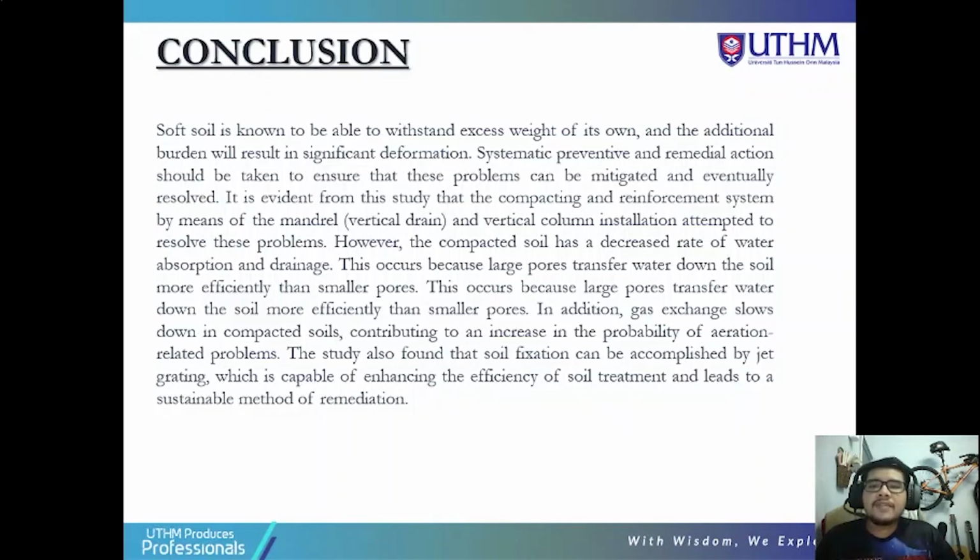It is evident from this study that the compacting and reinforcement system by means of the mandrel, which is a vertical drain, and vertical column installation, attempted to resolve this problem. However, the compacted soil has a decreased rate of water absorption and drainage. This occurs because large pores transfer water down the soil more efficiently than smaller pores.